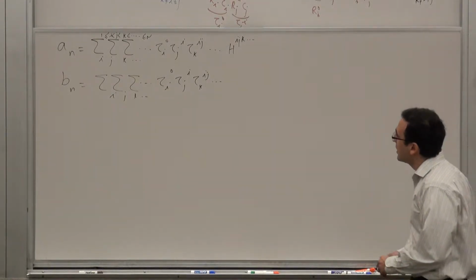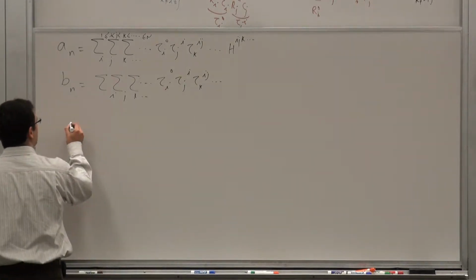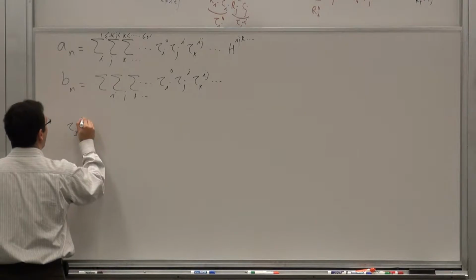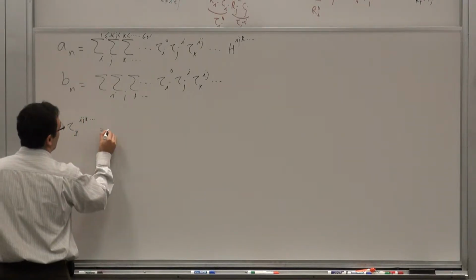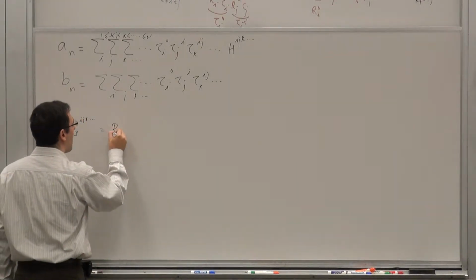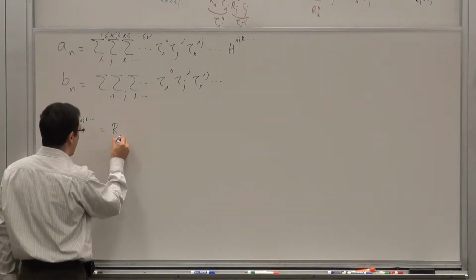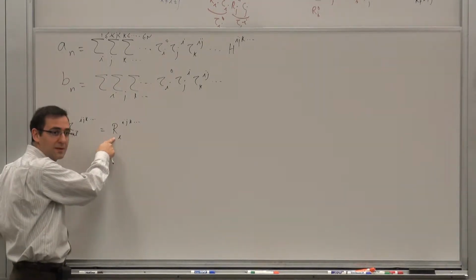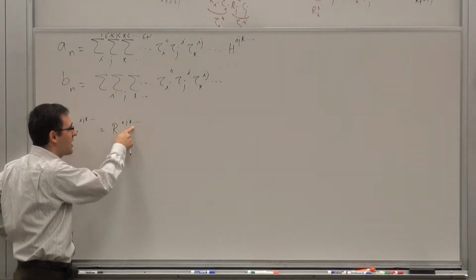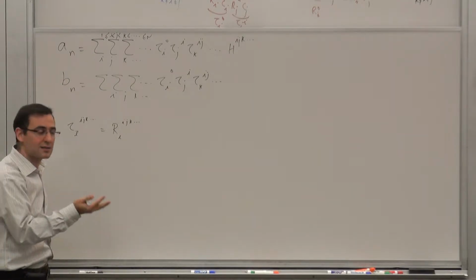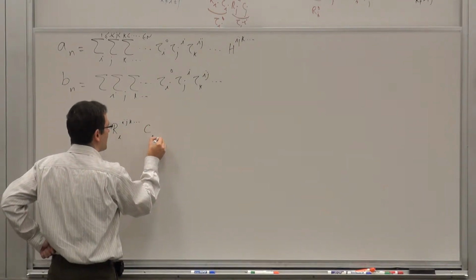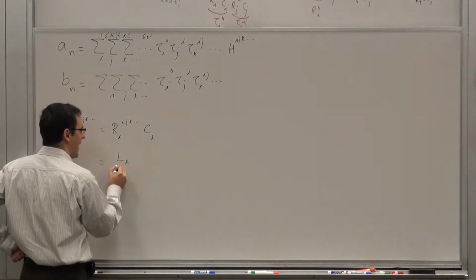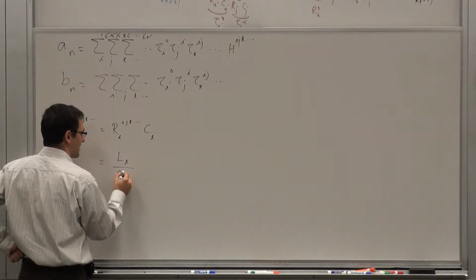And now the taus, if you have a capacitor, so for instance tau_IJK, etc., if it's a capacitor, it's going to be R_IJK, etc., meaning the resistance seen by element L, when ports I, J, K are infinite value, and everything else is zero value, everything that's not named, times C_L. And if it's an inductor, it's going to be L_L divided by the same resistance.